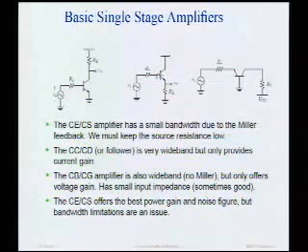That's because the voltage across the nodes are almost equal, so very little current flows into that capacitance, and therefore it's very wide band. Another way to look at this is the input impedance is highly degenerated, and so that feedback, the degeneration produced by RL, is basically going to reduce the input capacitance.